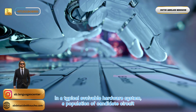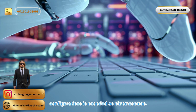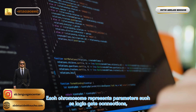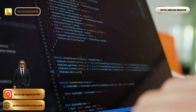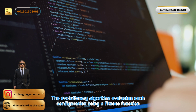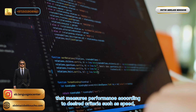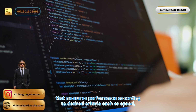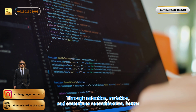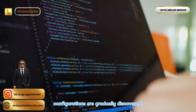In a typical evolvable hardware system, a population of candidate circuit configurations is encoded as chromosomes. Each chromosome represents parameters such as logic gate connections, routing paths, or functional blocks. The evolutionary algorithm evaluates each configuration using a fitness function that measures performance according to desired criteria such as speed, accuracy, power consumption, or fault tolerance. Through selection, mutation, and sometimes recombination, better configurations are gradually discovered.